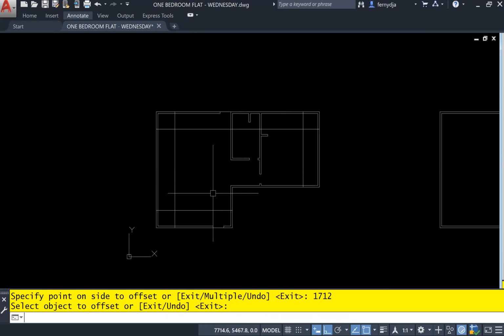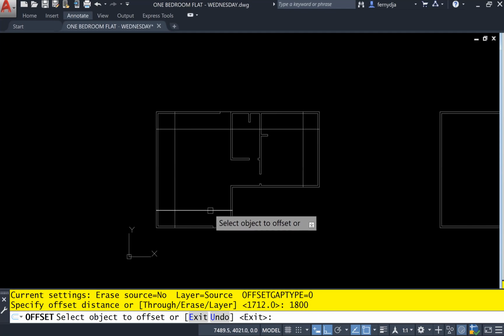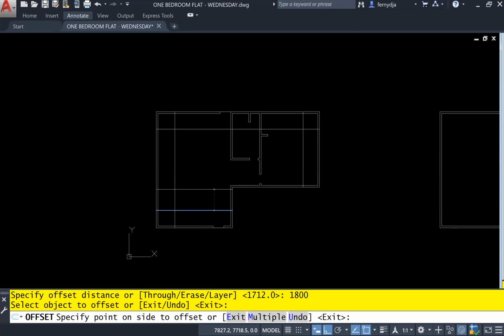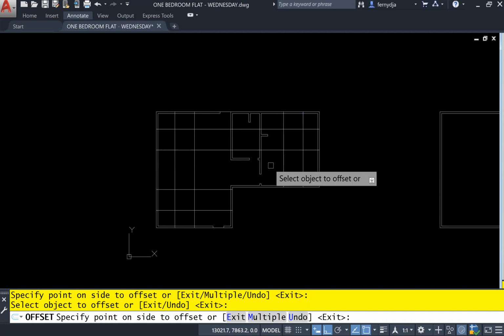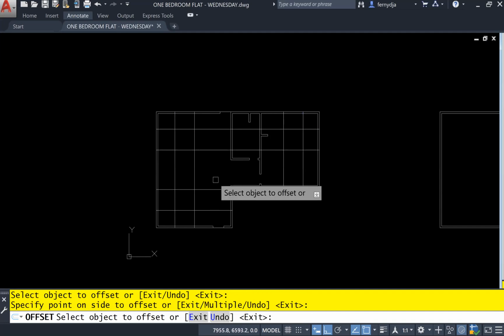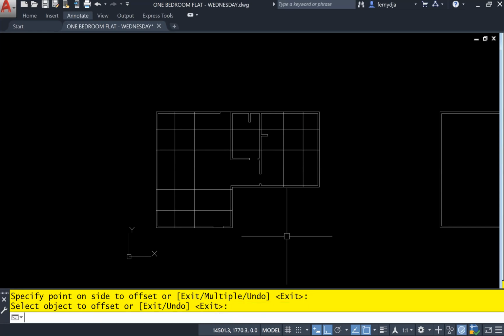We're in our last minute, so I'll just continue and then it will disconnect. So it's O, enter, or I could just press enter, enter. And I prefer to change the offset distance because it is the same again. So rather than doing override 4 times, we just offset 1800 going this direction. So the 4 lines that were offset, we're going to continue offsetting them 1800 going further in on the building. So we offset 1800, 1800, 1800, 1800. And I know that one of them is not 1800, but we'll come back and fix that. All right, so let me end the recording now so that we could resume afterwards.